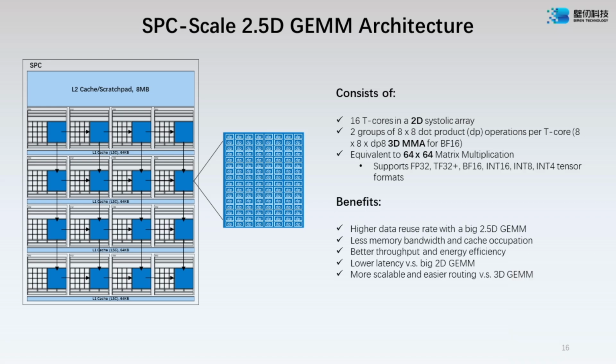Compared to a normal GPU's small tensor core, BR100 has better data reuse, compared to the huge GEMM from AI accelerators offered by Habana or Google. This GEMM has less granularity loss, 1/4 of the execution latency, and is integrated with the vector core.